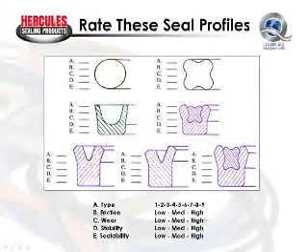Being a squeeze seal, the friction would be high, and the wear would be high. So being a squeeze seal with high friction and wear, we would assume sealability would be high. But what's the problem with our O-ring seal? Well, remember when we talked about shapes, we said that square is better than round and rectangular is best.